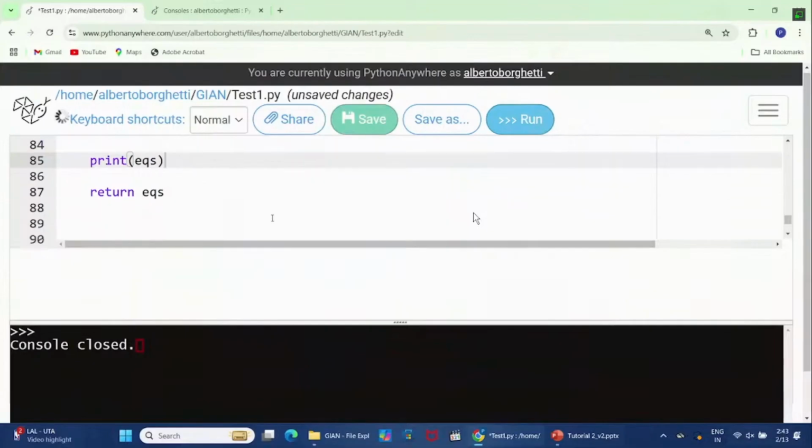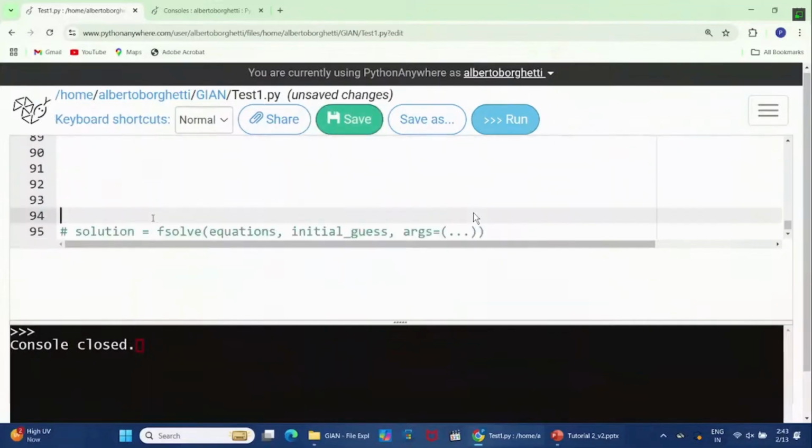Now we can use our fsolve. You see that we have put a comment at the beginning in order to understand what we have done in these equations. We need also to give this fsolve a first tentative solution, and we can use the usual way to put as an initial tentative solution the first values that we have, so 1 and 0: modulus 1 and angle 0 for both bus 1 and bus 2.